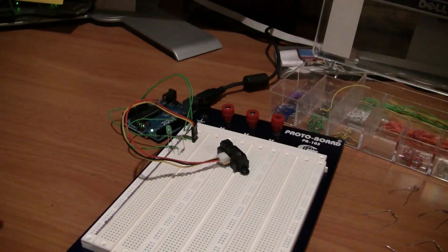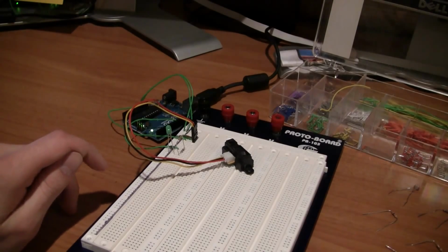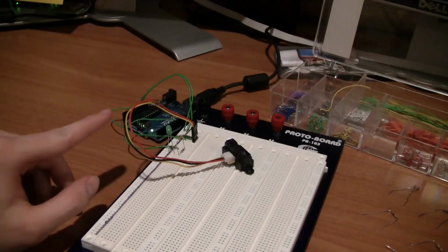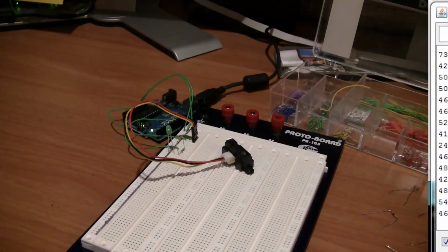All sensors that come like this will usually have 3 wires, a voltage wire, a ground wire, and a sense wire. The red wire, we give it 5 volts. Ground gets connected to ground, of course. And then the yellow wire returns a value between 0 and 5 volts that we can feed into the analog to digital converter in the Arduino and use it to measure a distance value. You'll often notice that these kinds of sensors will give you a broader range because they've already designed it to operate on the whole 0 to 5 volt range. You can also buy these sensors in 3.3 volt iterations and other voltage versions.